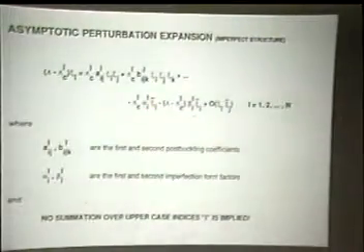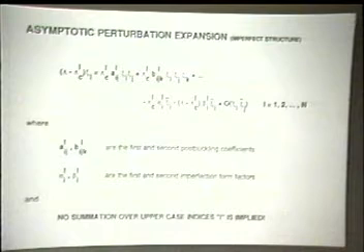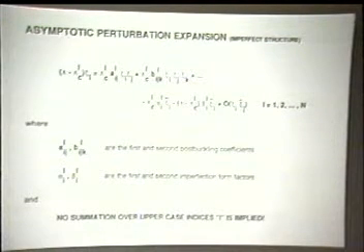And we have also n minus 1 times n response problems, which we have to solve. Now, let us look at, since we are interested in the behavior of the imperfect structure, Koiter's idea was that if the imperfection is sufficiently small, then he does a Taylor series expansion of the behavior of the imperfect structure at the bifurcation point of the perfect structure, and he hopes by this Taylor series, by keeping the first or maybe the second order term, to get enough information about the location of the limit point.